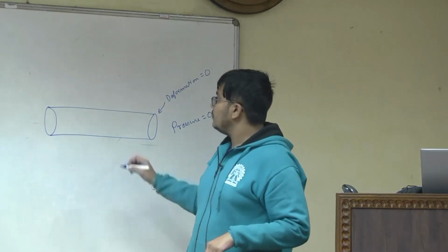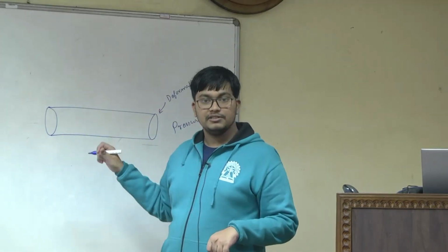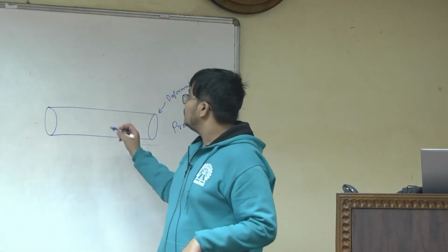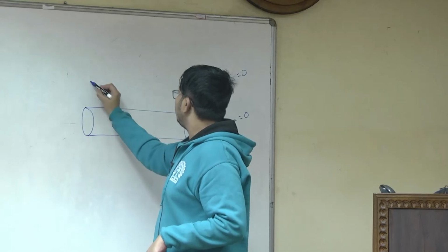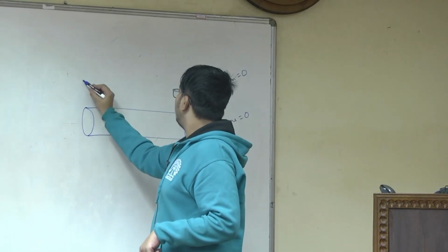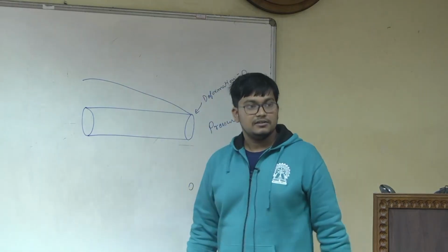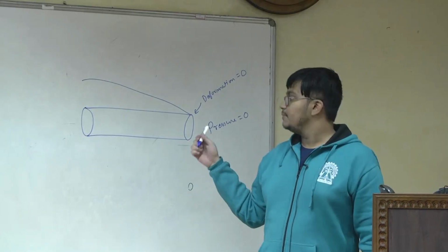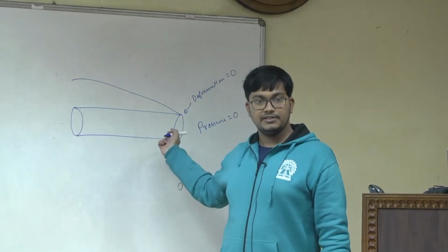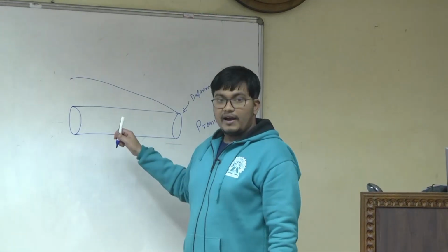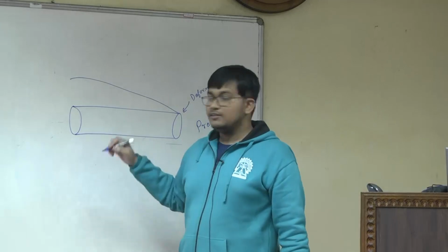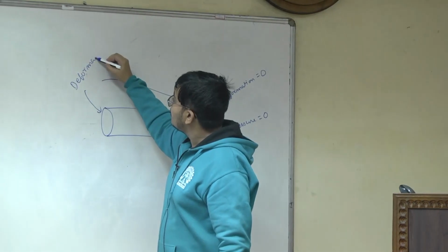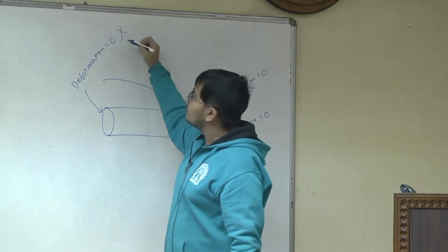So if you look at the theory, yesterday Suman sir talked, I think, about the analytical solution of the deformable wall microchannel. So the deformation profile actually looks like this. Like if this is the wall, the wall will be looking something like this. So at the inlet there will be maximum deformation, and at the outlet there will be minimum deformation, because at the inlet the pressure is more and at the outlet the pressure is less. But for Ansys, since we require another boundary condition, we will be forcefully prescribing in this wall the deformation to be equal to 0, which is actually not correct.